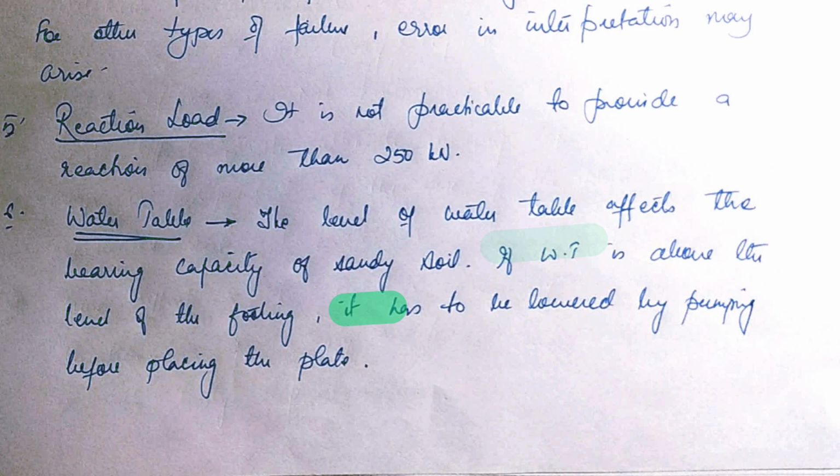So, if the water table is above the level of the footing, it has to be lowered by pumping before placing the plate. The test should be performed at the water table level if it is within about 1 meter below the footing.